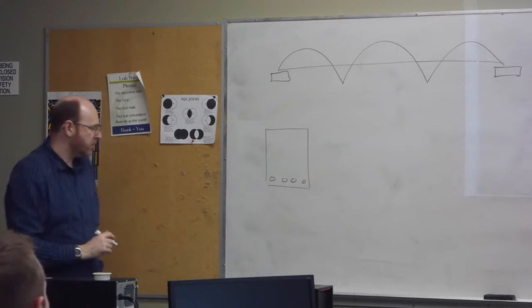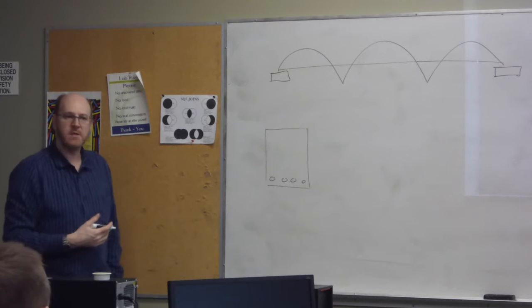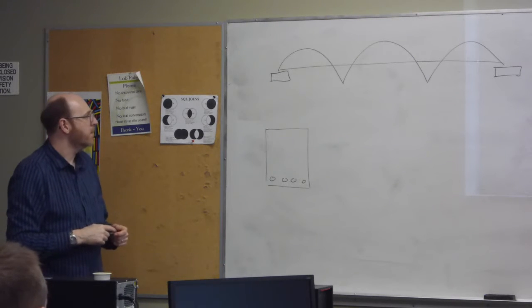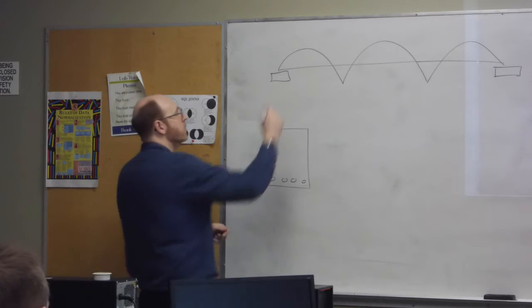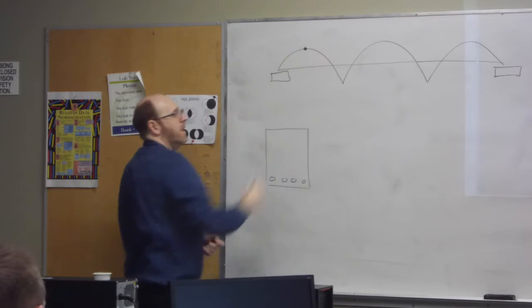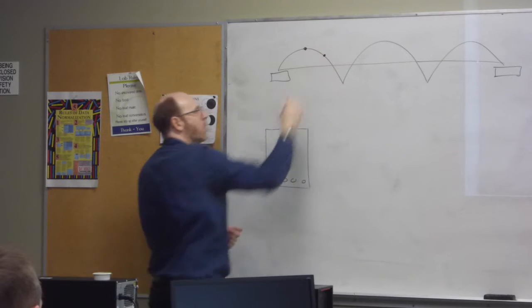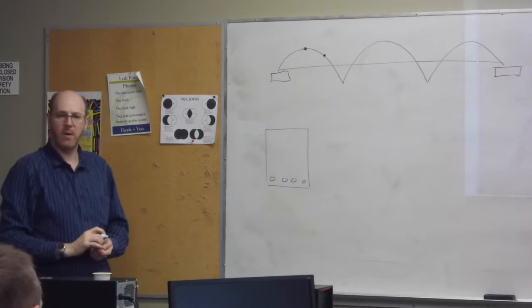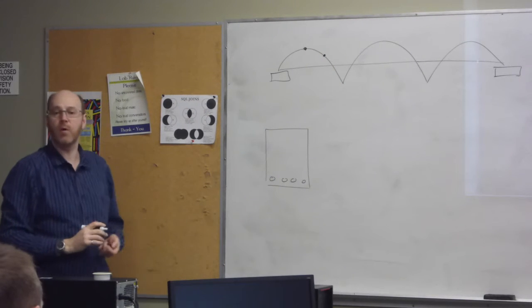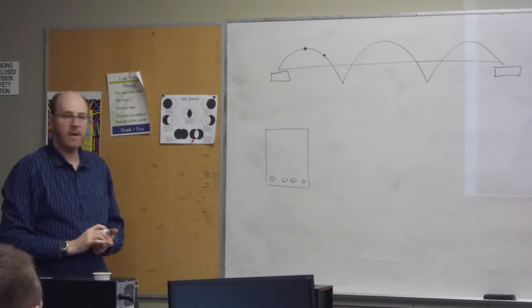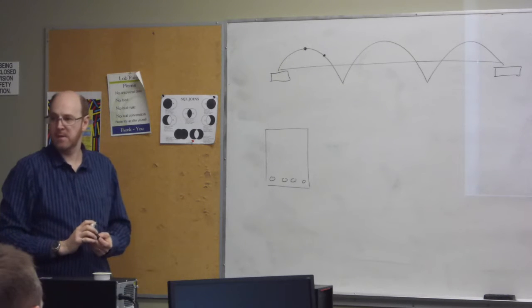Now we still have all of our spacing checks and what have you go through on here, but this would apply to that specific value. Well, out here, the moment resistance is less. So I wouldn't necessarily need all 4 bars in that location. I could get away with using 2 bars, right?